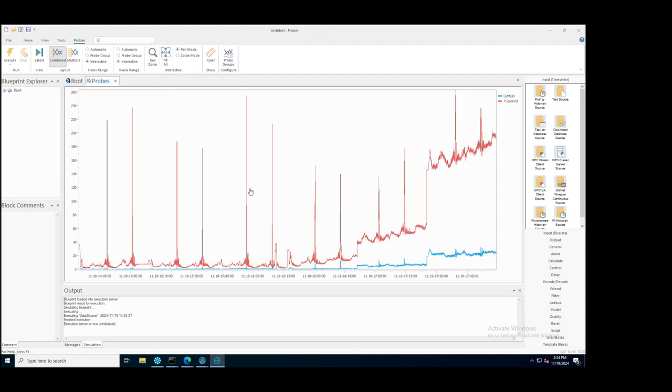And here we can see, well, the first thing we see is that we do have a degradation over time in the t-squared especially, as well as the distance to the model. And we have these peaks, which might be a bit strange, but actually what this is when the blade is speeding up and slowing down between different cutting phases. We experience this abnormal or non-linear behavior, right? And that's why it's being highlighted as abnormal. But we're not actually too worried in these peaks.